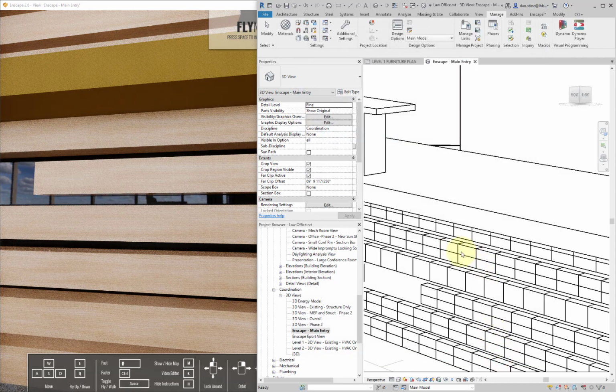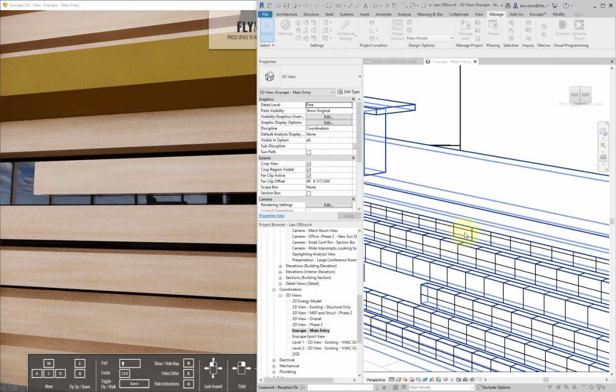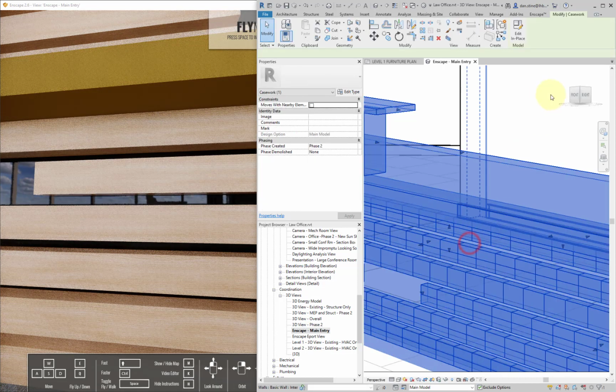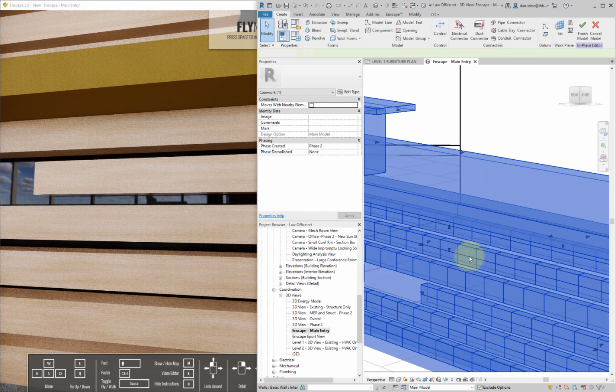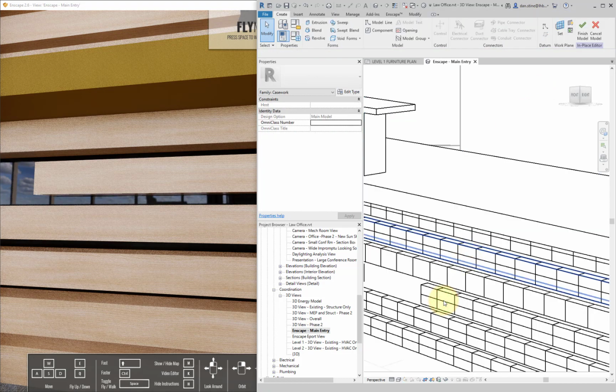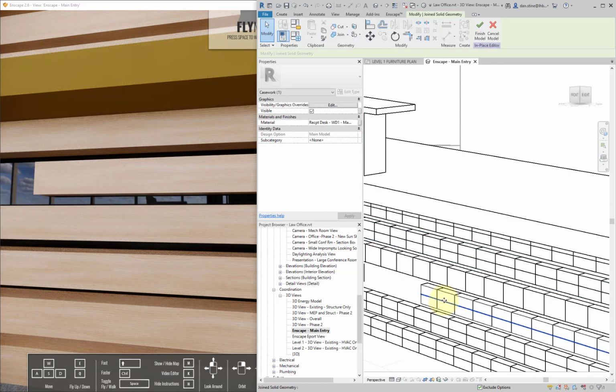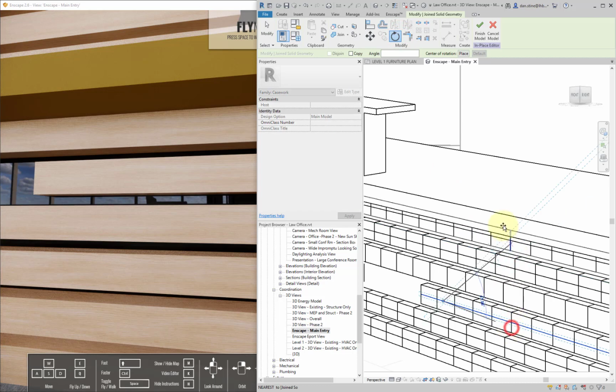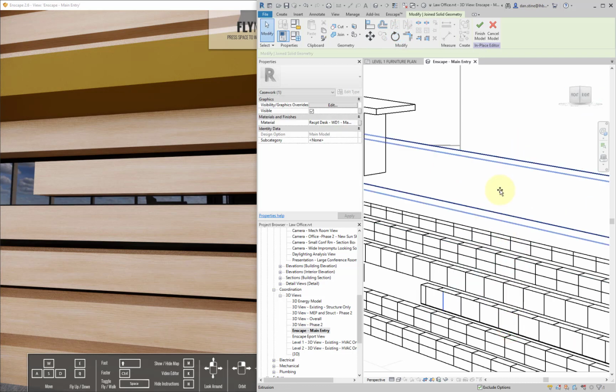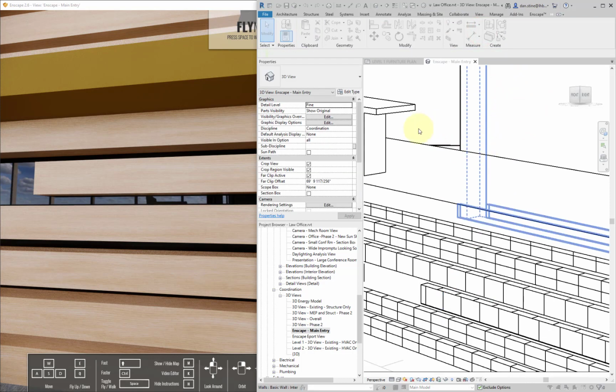And when you can see a fill pattern like this, we'll select this group and edit group. That's the first thing we have to do. And then I'll tab in. Revit lets you select a model pattern and rotate it. So we can rotate this 90 degrees and then finish the edit in place.